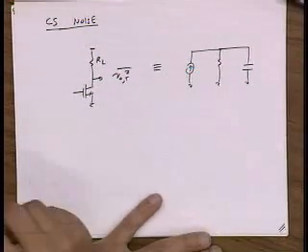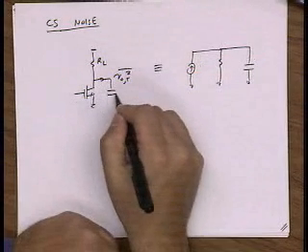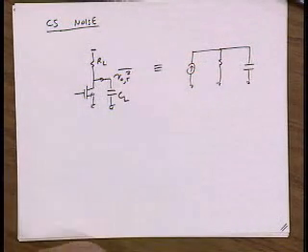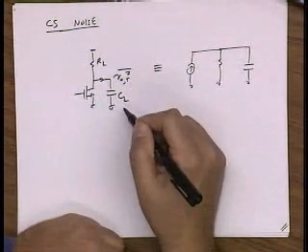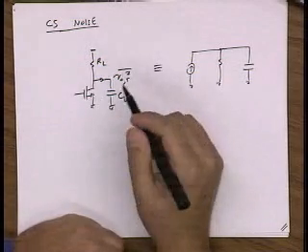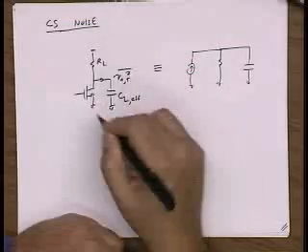In these analog circuits, typically we have a large capacitor at the load, CL, which more or less dominates the transfer function, so the bandwidth is determined by CL. That actually simplifies things. Let's call this CL effective, the total capacitance sitting on this node.